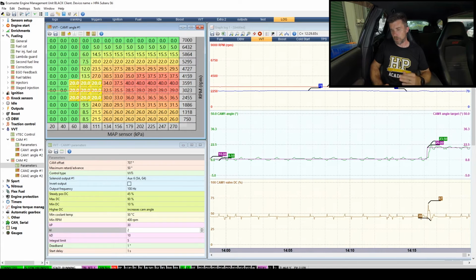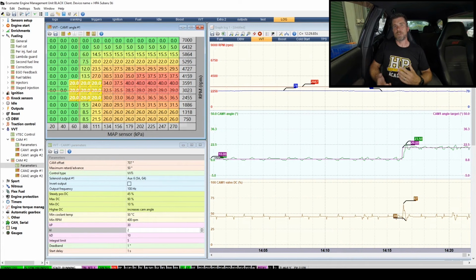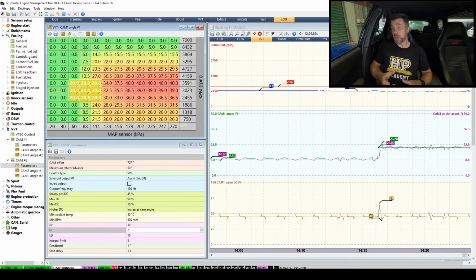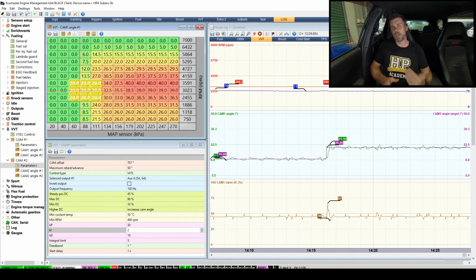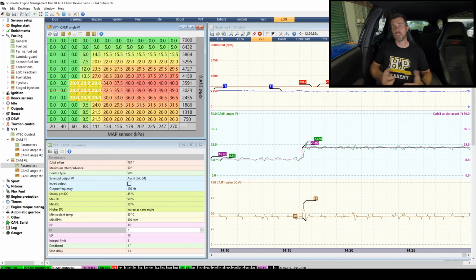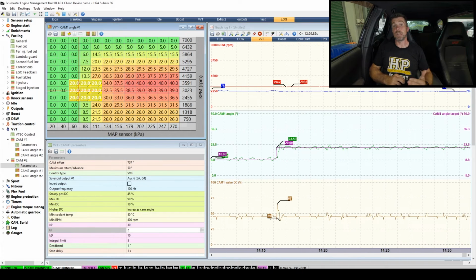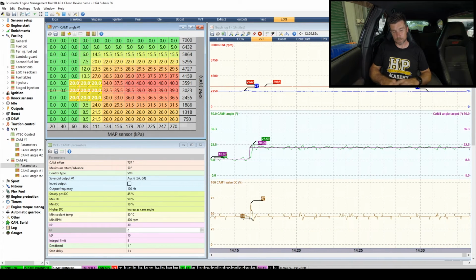Got a little bit of an overshoot there, so there may be the ability to play a little bit further with the combination of our proportional and our derivative gains, but certainly the response, the amount of overshoot, and how quickly that is resolved is going to give us really good control, and our cam system will work.